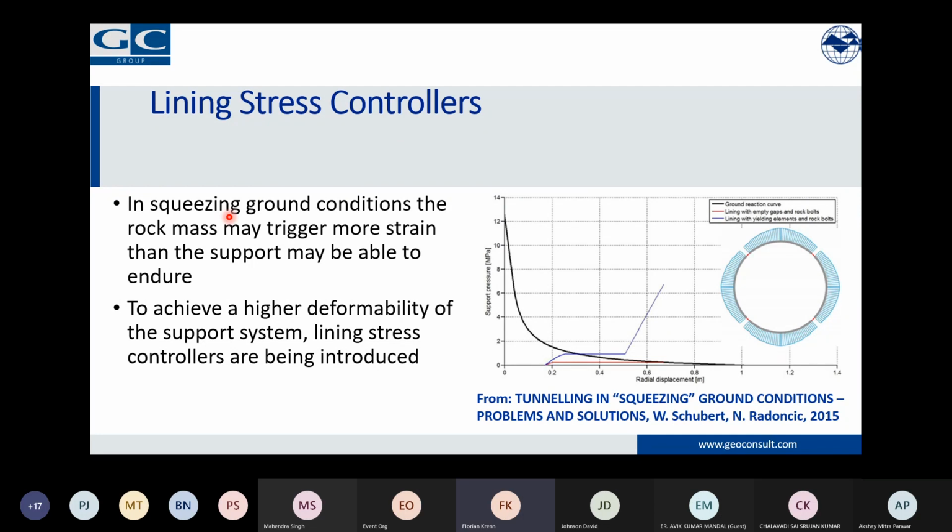So sprayed concrete will go up to 1%, maximum 2% strain, and then we have taken all the reserves. Because these reserves are the early creeping, the development of strength and resistance of the sprayed concrete, but a young sprayed concrete can endure some strain, much more than a normal concrete can do. But also there are limits.